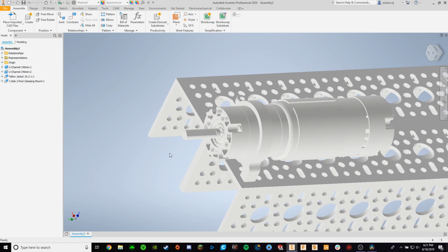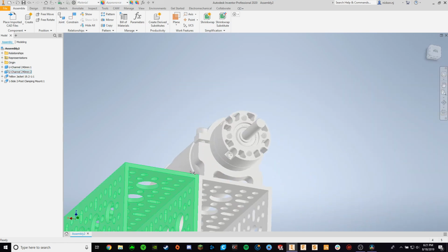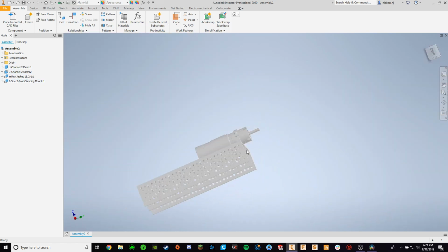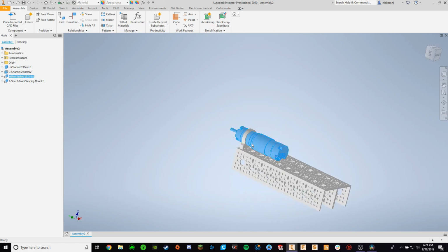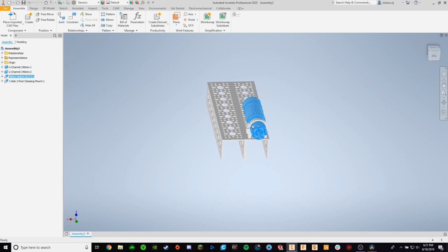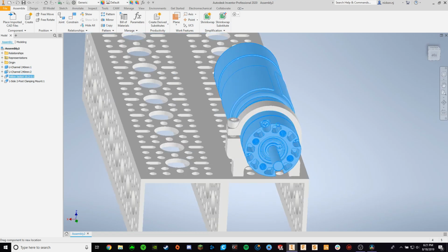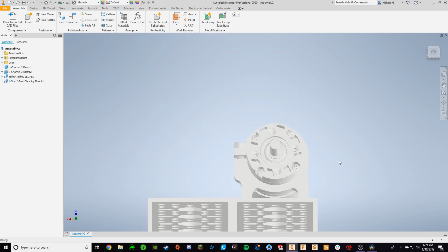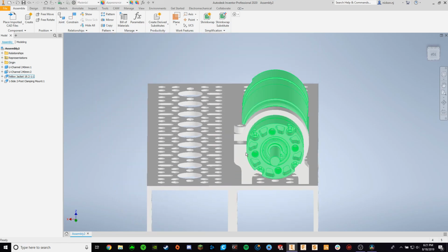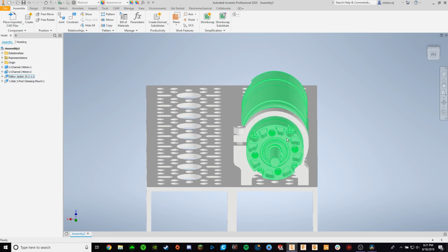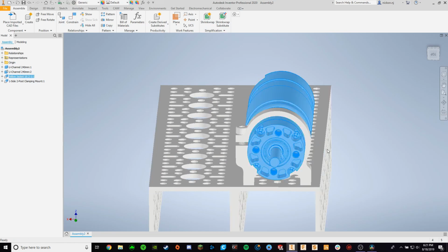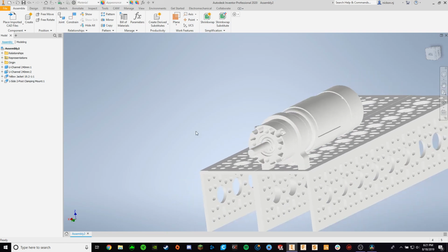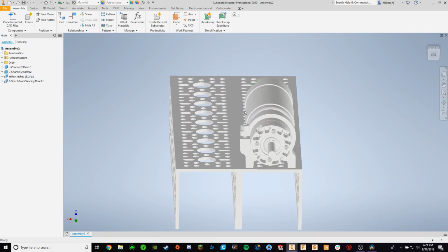it's not fully constrained within the clamp mount. And so you might think, okay, how am I going to constrain this on this rotational surface? And for this, again, it doesn't really matter because it's an orbital motor. Let's say this was a spur motor, then the center point of your output shaft would be rotating around the center point of the clamping hub. So then it's pretty important to have your motor anchored in a certain position.